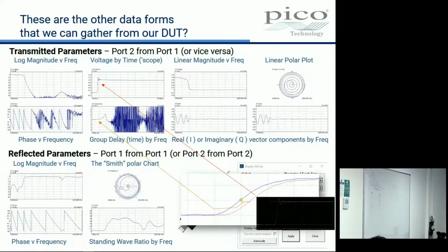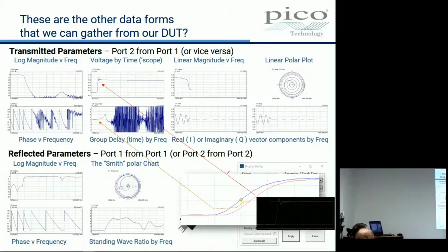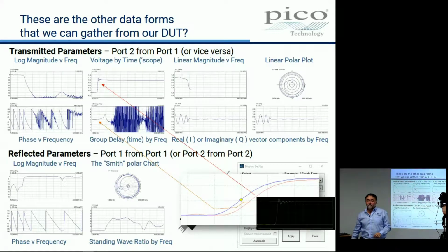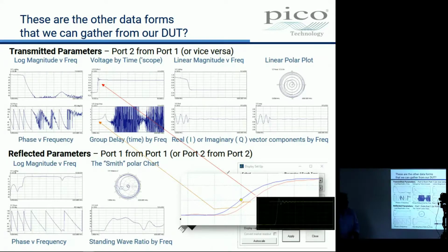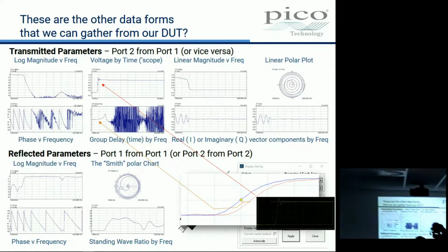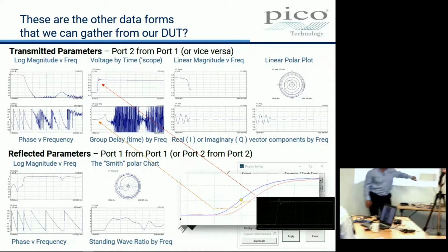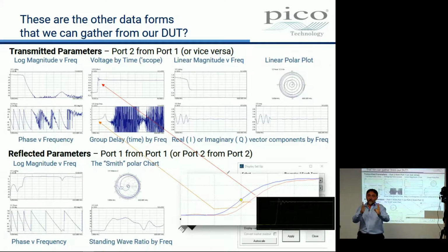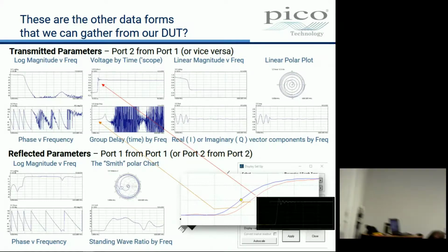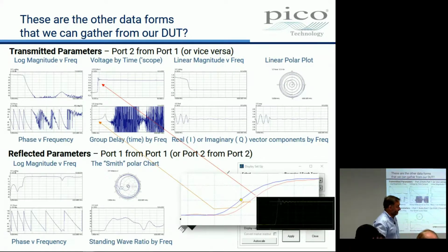And we saw it, didn't we? We saw it on our pulse when we looked at, here it is, look. The pulse shape has been corrupted. You'll have to remember it's not very visible here, but we had this ringing. And this is due to the way the filter rolls off, and the fact that group delay is sliding all the harmonics with respect to one another.